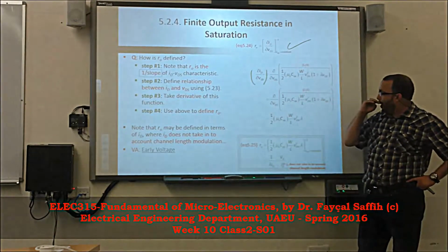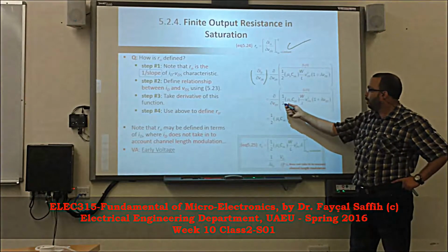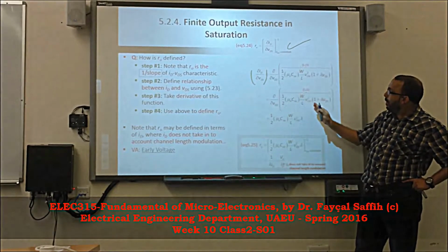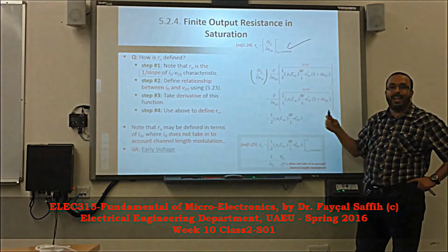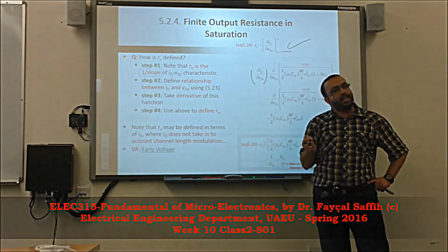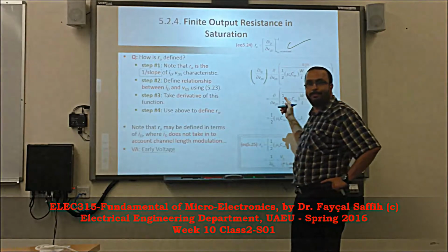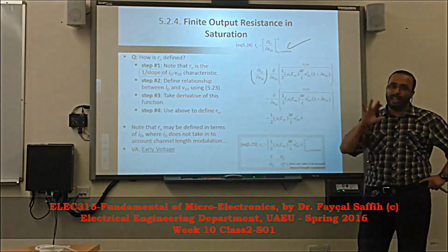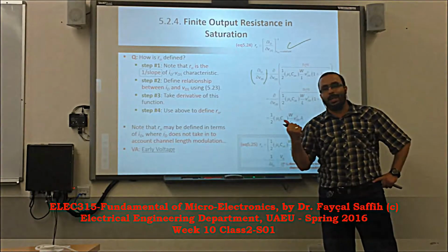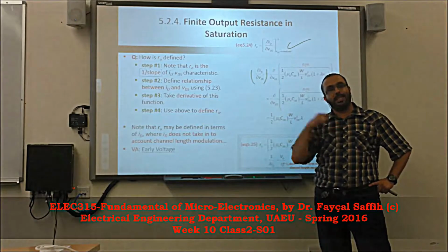Deriving, we are not bad in math, right? Well, good. So we take this. Of course, when we derive, the variation of lambda, we said that VDS will change, lambda changes, yes or no? We take that variation and put it in L, in lambda. Okay? So we said, I want to keep L the same, but I want to introduce the parameter lambda where I have this relationship between VDS and ID.